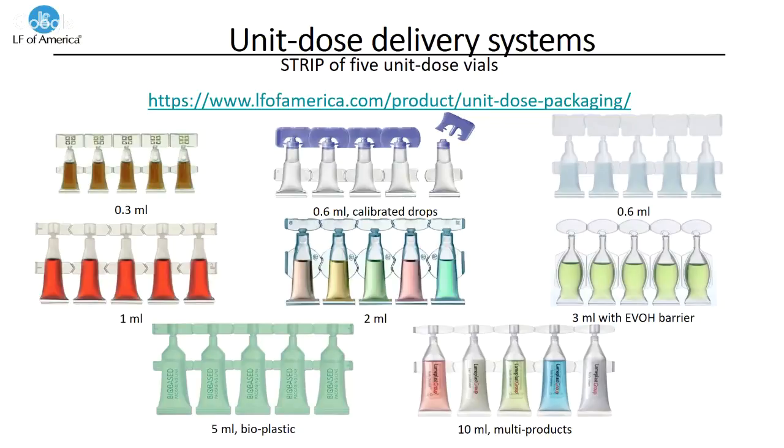Basically, once you open the packaging, and this, by the way, is a tamper-evident cap, you have a perfect, clean orifice with no plastic imperfection, no plastic tears. This gives you the plus of being able to deliver exactly the same quantity of product. So you have a consistent delivery of, in this case, 0.05 milliliter calibrated with standard water. This is very important, for example, for ophthalmics, when you are delivering the same amount of active, the same amount of API in both eyes. It's an advantage that other technologies in the market, when you go with blow molding as opposed to injection molding, cannot achieve.